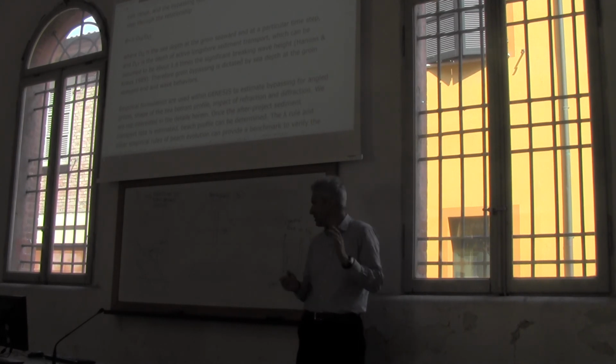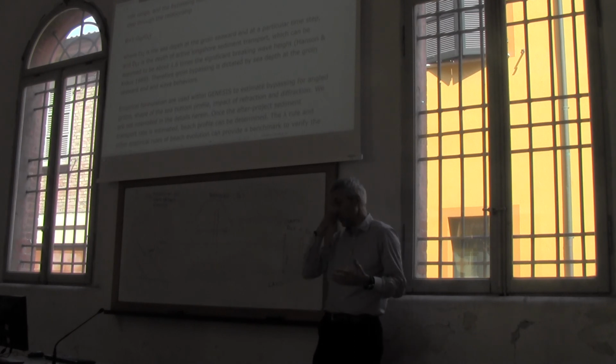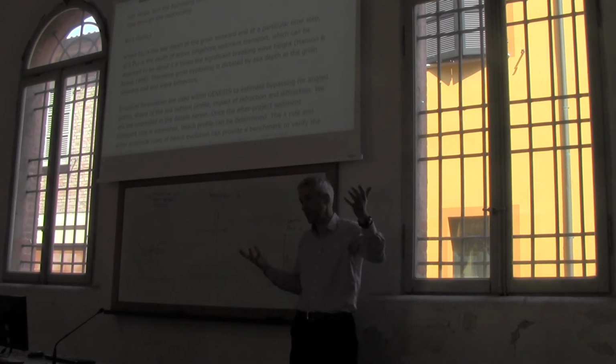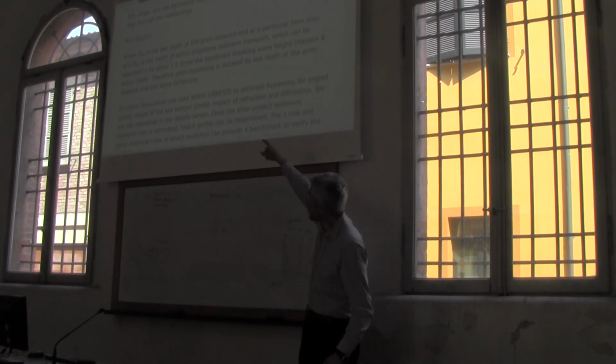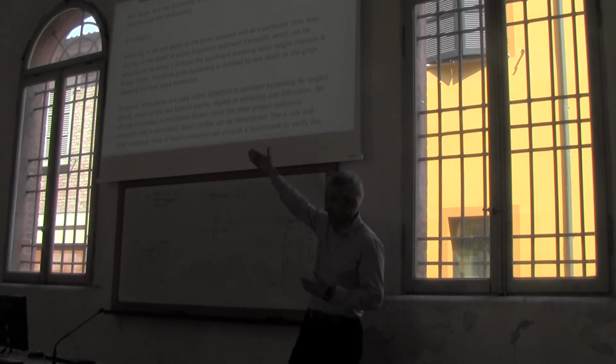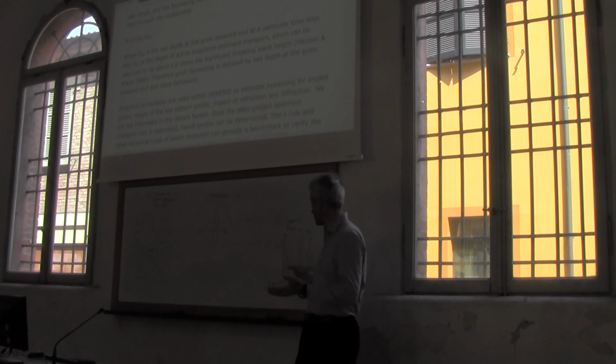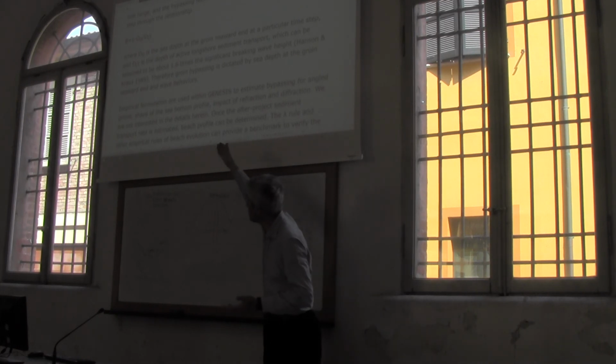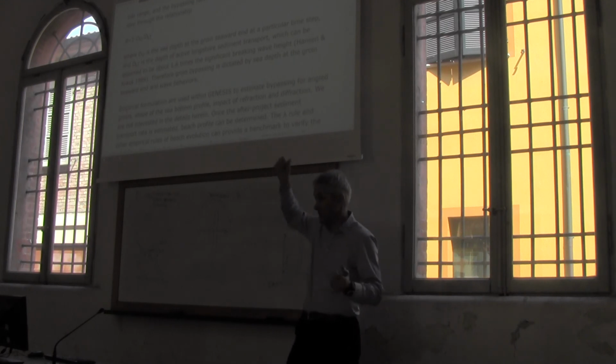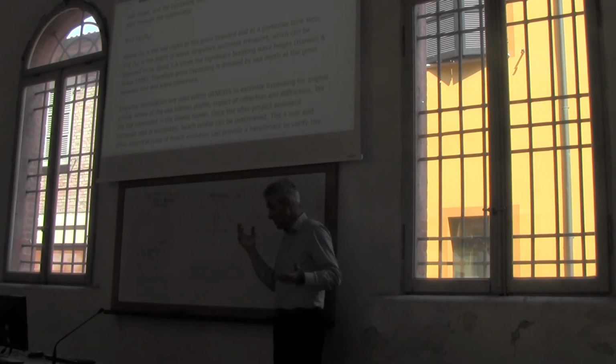So in order to reduce bypassing to zero, you don't have to go up to... it's not linear. This relationship seems to indicate that it's linear. It's not linear. I mean, the reduction that you get in longshore sediment transport is not linearly related to the extension of the groin, like it seems from there. Because bypass is linearly dependent on the DG, which is not.